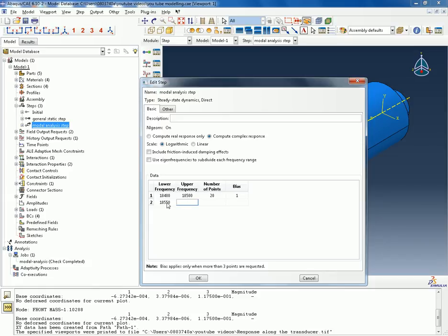You could also use imaginary values for excitation. In this demonstration, I'm just going to use the real part of voltage. This is the back. I'll keep it the same, 0. This is the front of the first one. I'm going to set exactly 50 as well, and the back of the front disc will get 0.